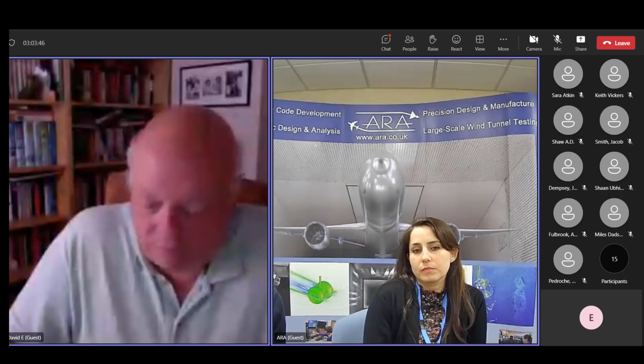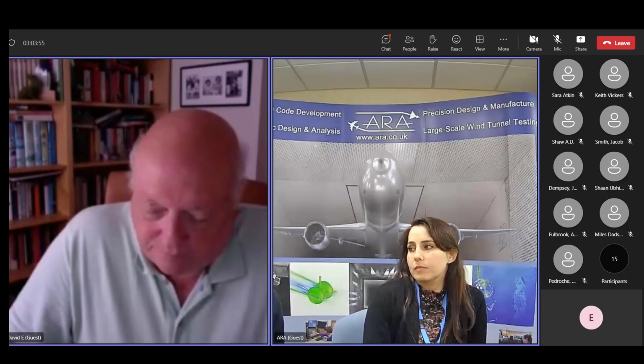So we allow for the effects by applying them simultaneously during the calibration and taking them into account in the mathematical model, so that when we output say axial force from the final test, it is pure. That is a pure measurement of axial force. It doesn't include normal force, which has already been taken out, and then there's a normal force that would be output separately.